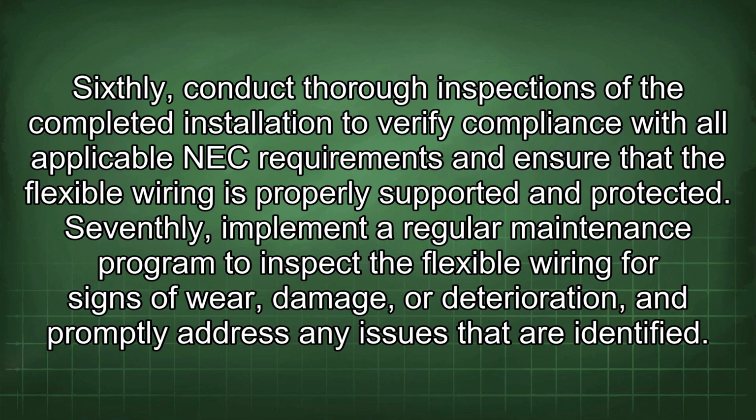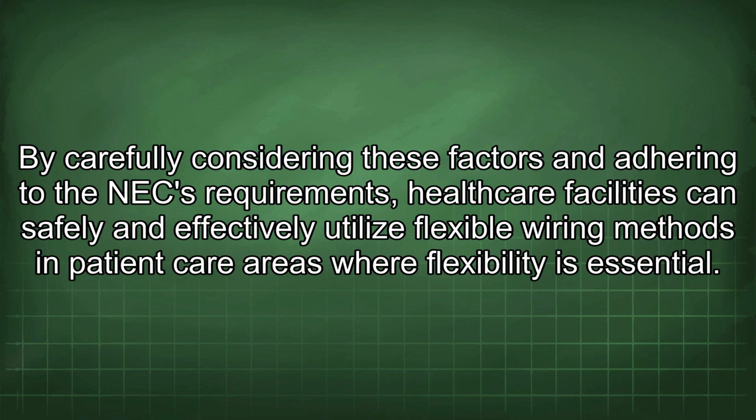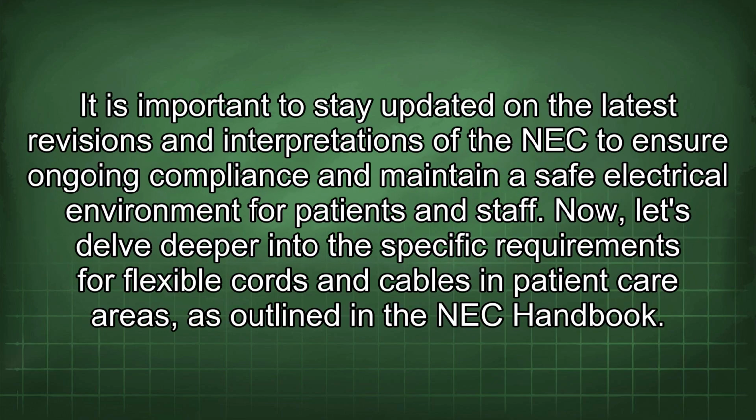Seventhly, implement a regular maintenance program to inspect the flexible wiring for signs of wear, damage, or deterioration, and promptly address any issues that are identified. By carefully considering these factors and adhering to the NEC requirements, healthcare facilities can safely and effectively utilize flexible wiring methods in patient care areas where flexibility is essential. It is important to stay updated on the latest revisions and interpretations of the NEC to ensure ongoing compliance and maintain a safe electrical environment for patients and staff.